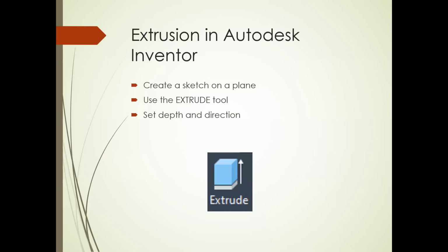You're going to create a sketch. That sketch has got to have some kind of limitations to it, right? So once that sketch is fully defined, or if it's fully enclosed, and that's going to be another huge word for you there, it has to be a closed profile, and then we can make a solid. Now, there is one exception there. Solidworks does have a tool where you can do some other things, but just in general speaking, we do have to typically have a closed sketch, and then we're going to extrude it, and then we're going to set the height and the depth. So that's exactly what you see me do in AutoCAD here.